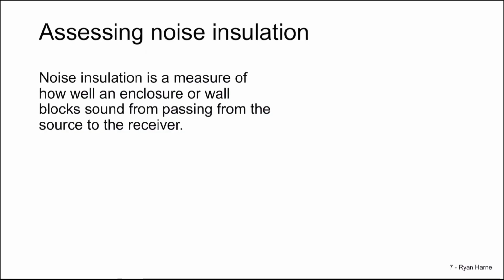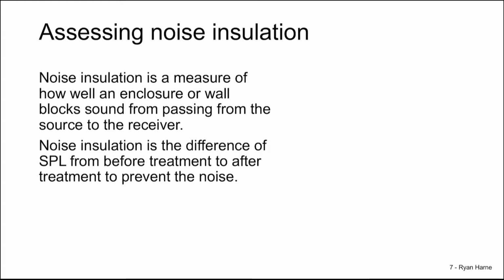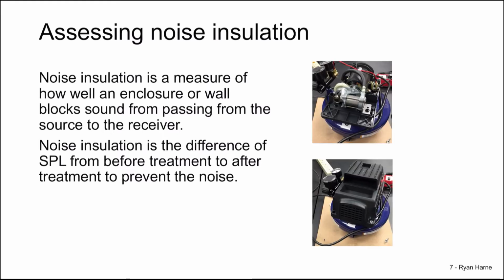Our first use of a sound level meter in this course will be to assess noise insulation. Noise insulation is a measure to assess how well an enclosure or wall blocks sound from passing from a source to receiver. It is computed as the difference of SPL from before to after treatment. Take, for instance, this air compressor.